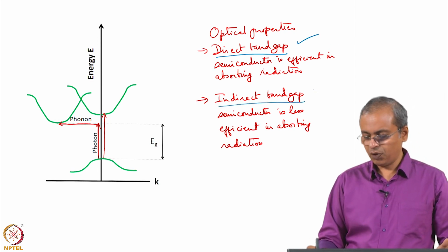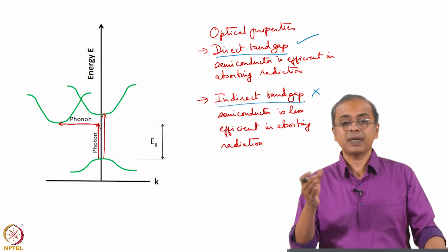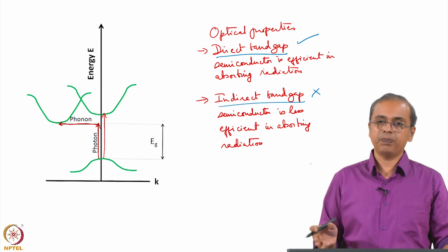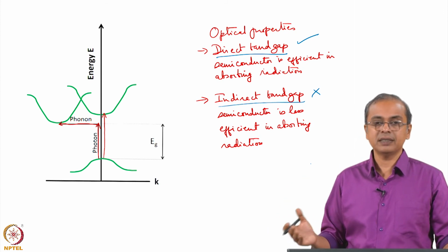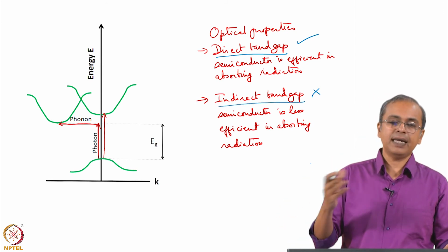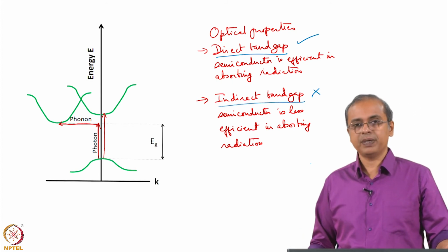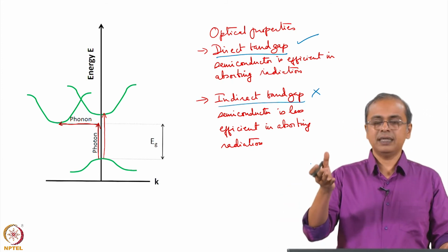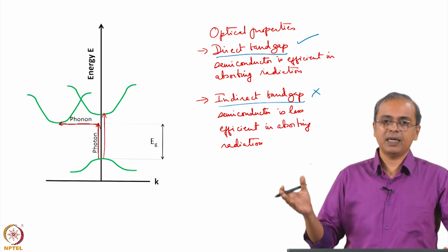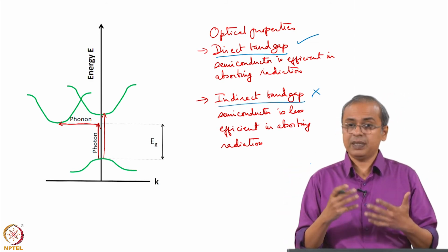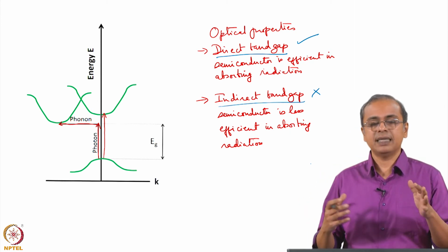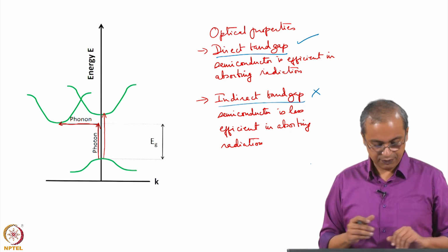This, on the other hand, we would not prefer to pick unless there is some other commercial reason why we would need to pick that. So, for example, silicon is actually used quite a bit for solar cell applications, but in fact if you look at it, it is an indirect band gap semiconductor. It is not a very appropriate material to use, but simply because it is available commercially in large quantities and in a sense relatively cheaper. It is not that cheap, it is relatively cheaper, and therefore people end up working with that.